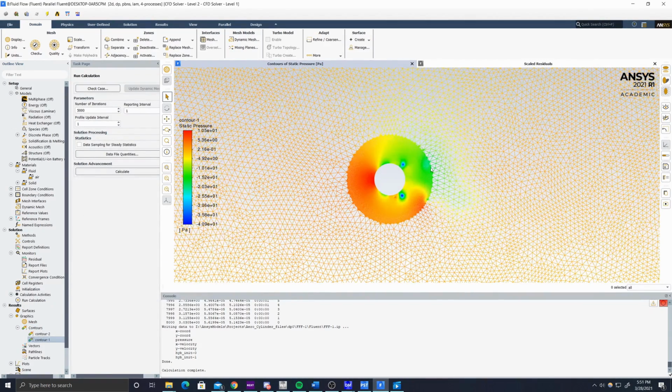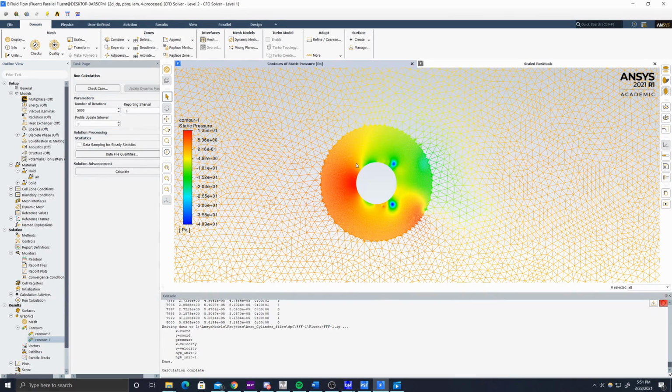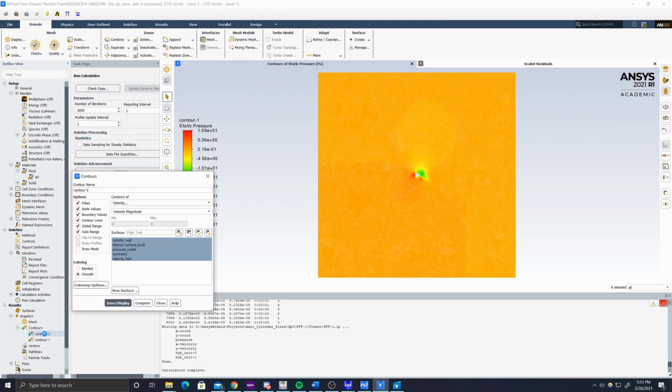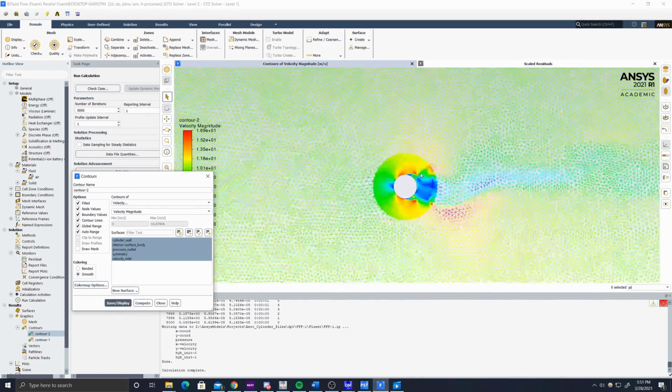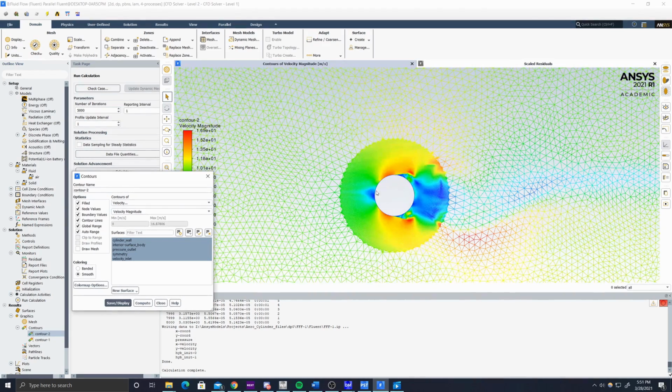Okay, so we see in this region that we have a large pressure difference on both sides. We have some drag with a large wake region. It's a lot more apparent in the velocity graph as well, which makes sense for a laminar flow and the stationary cylinder. We're just going to keep going. You'll see the same thing in the streamlines.